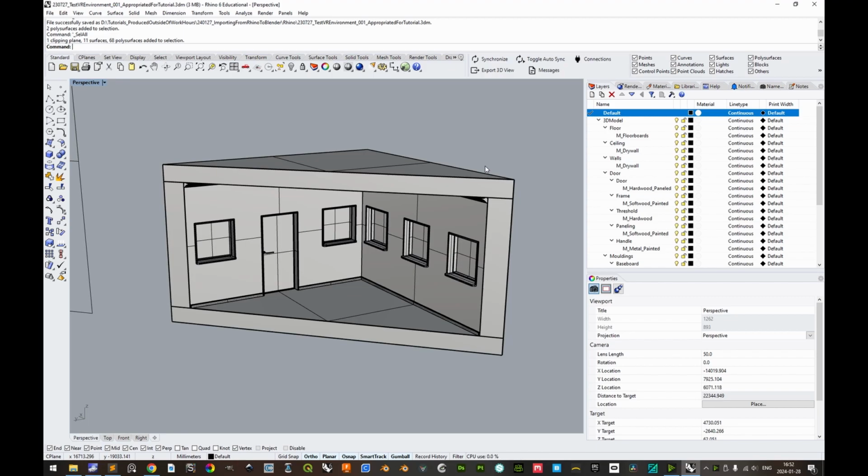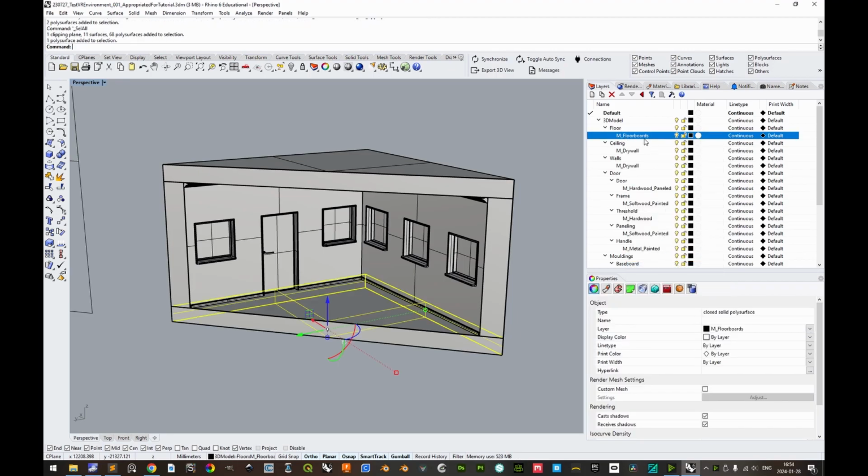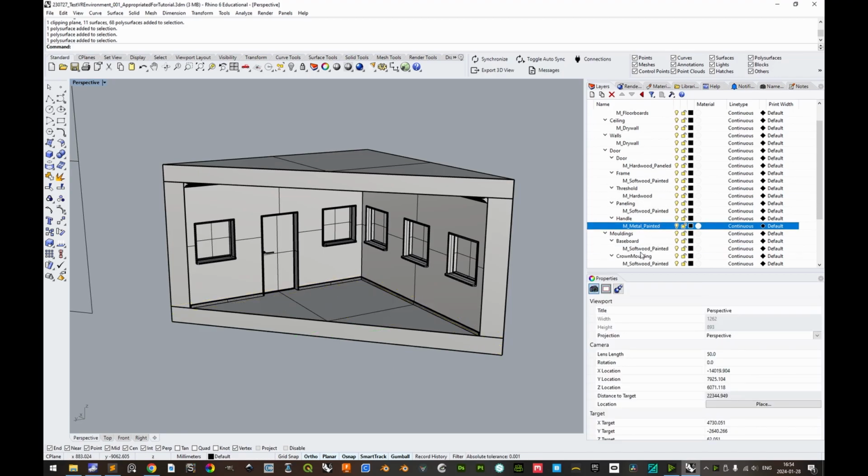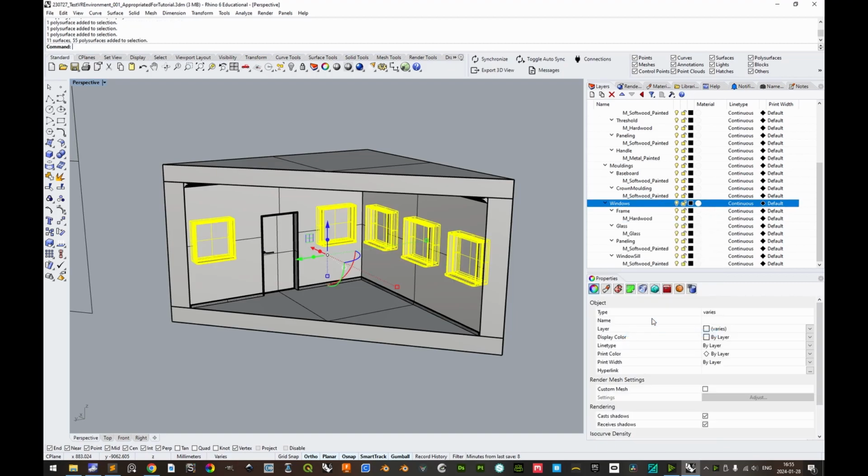The main assumption for this workflow is that you do the 3D modeling and the intended material slot assigning here in Rhino, and UV editing and shading in Blender. You don't need to order your layers in a nested logic like this, as long as you have the actual objects in a layer with the m_ prefix, because it is only the utmost layer in the hierarchy that will be used in Blender for the material slots, but with this nested logic you can easily select, as an example, all window sub-objects, although they are intended to have separate materials.